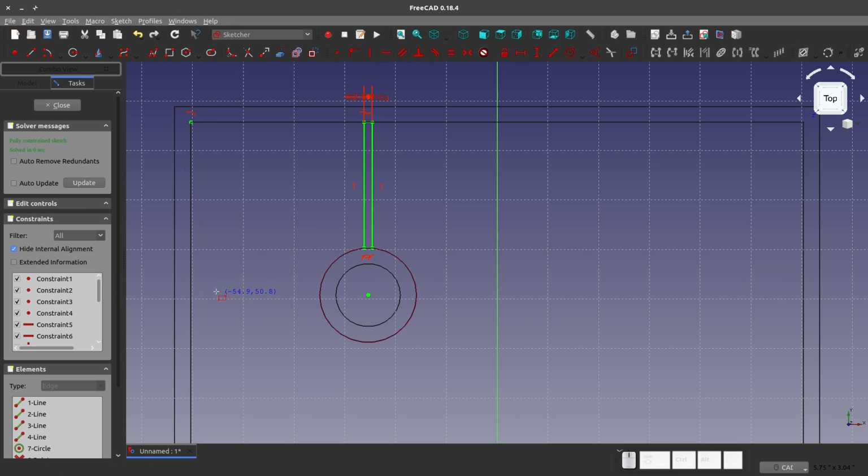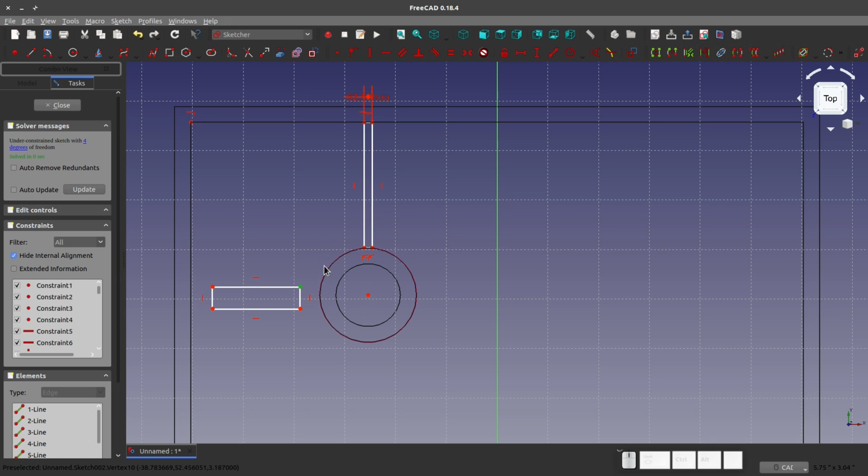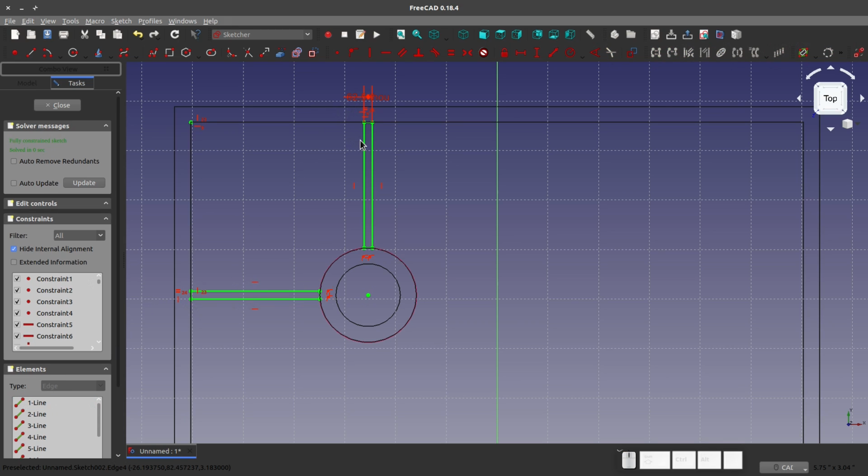Oops, but I want a rectangle. And we're going to make this coincident and vertical and equal. Right? So these lines are equal. That way with the design intent they can change thickness together if that gets updated.